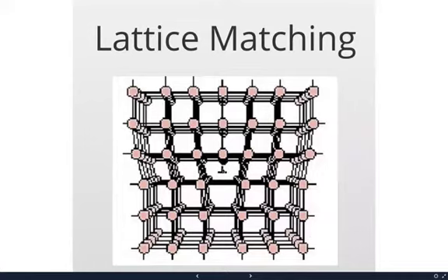one atom, or if you add an extra atom, for instance, as you're growing from top to bottom, here you added an extra atom, and that causes a defect, and it starts stretching the bonds, as you can see here. And this is a very big problem for a solar cell because electrons and holes can get trapped by these defects, and that will drastically affect the performance of the solar cell.